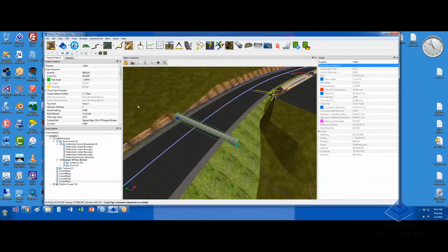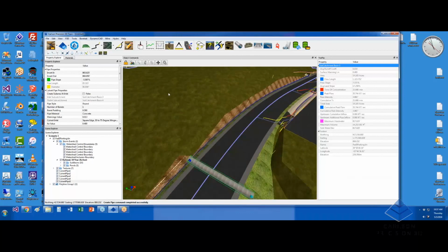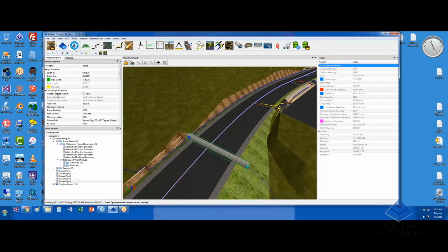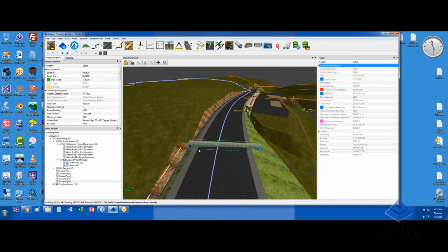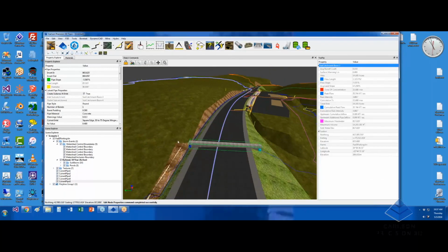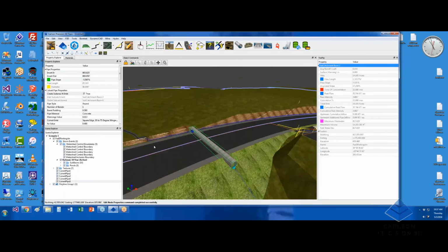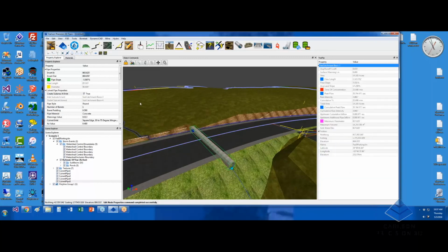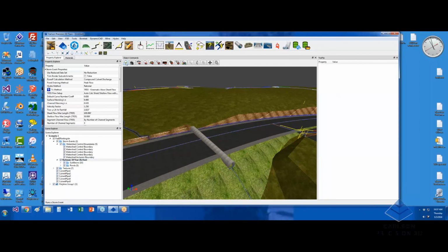But if you turn on this create sub area at inlet and turn that on, what that does is that will force a sync point here, and it will only look from here and up as to what is actually contributing to it. So if I recalculate the storm at this point, this is yet another way that you can control watershed boundaries, because culverts by definition need to take water in from one subbasin and then exit water in another one.